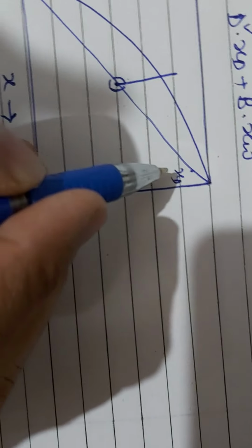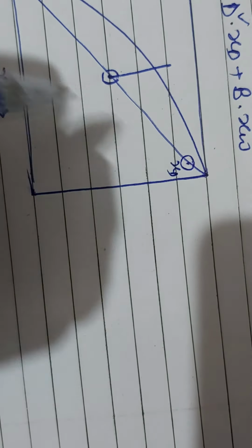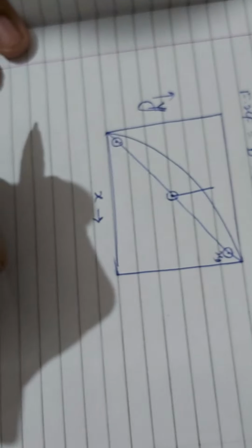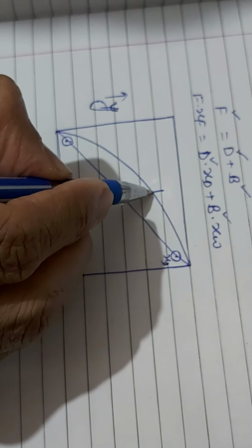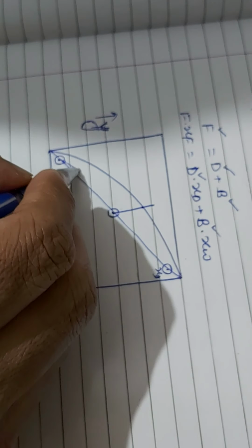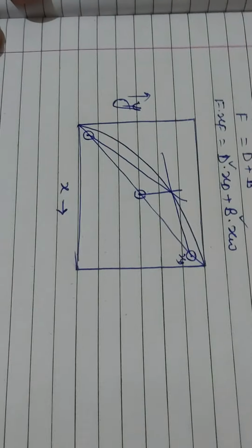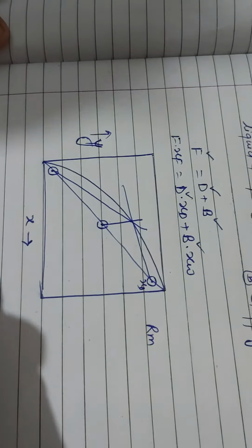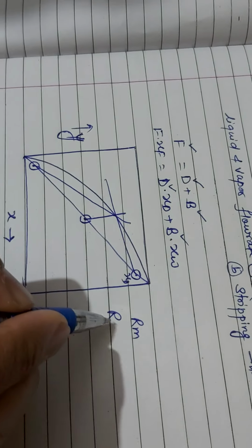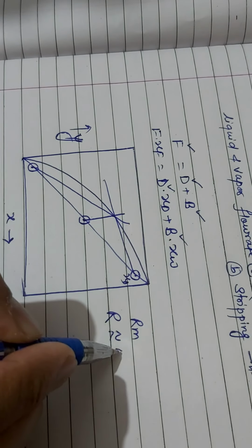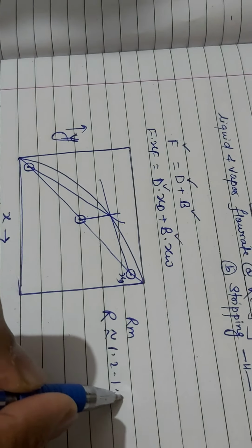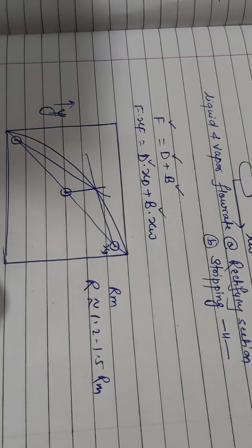Here you look at XD, the distillate. This is for the bottom. Wherever this meets the curve, you draw a line which will give us the minimum reflux ratio, Rm, and we are aware the actual reflux is normally 1.2 to 1.5 times the minimum reflux ratio.